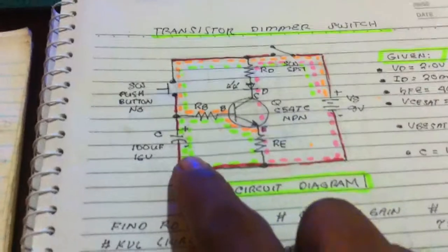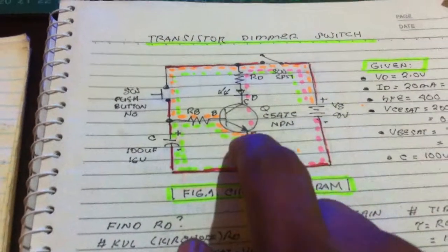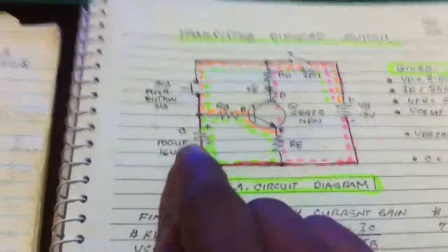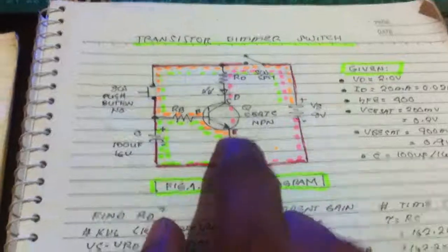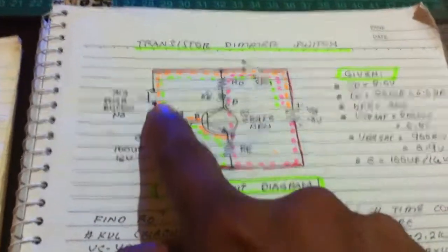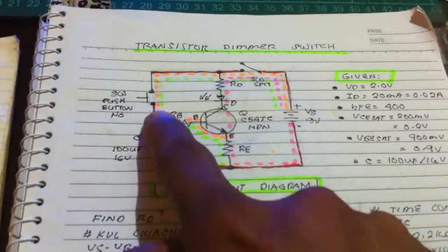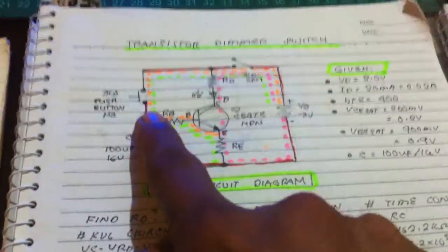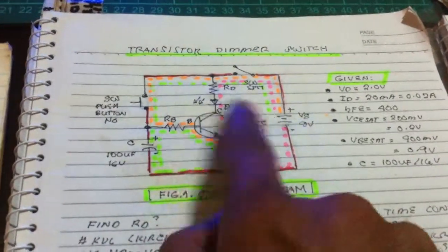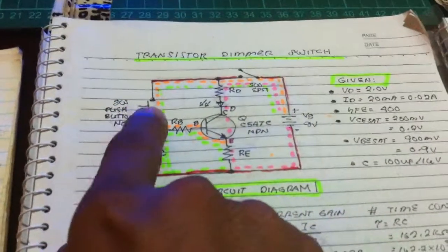So what happened here is the circuit is still not stable. I replaced the resistor here with the capacitor, making the switch floating, an indeterminate state. It has no state. It should be 0 or 1 because this is some sort of buffer gate. There's no input.